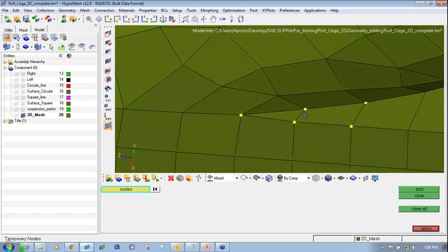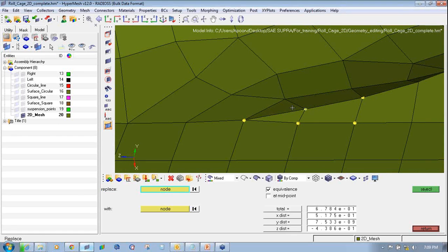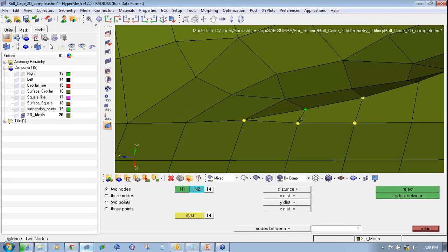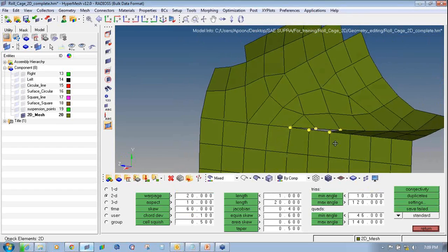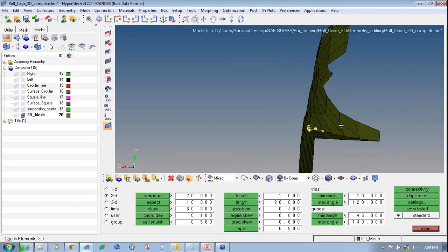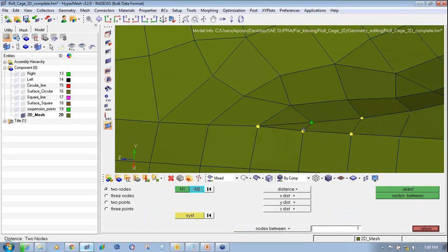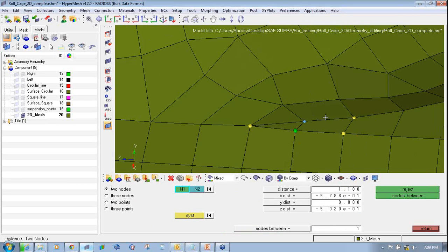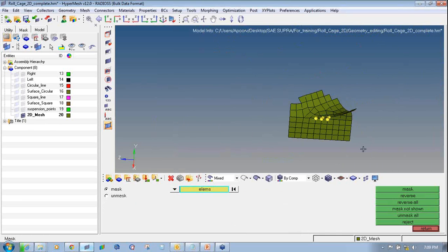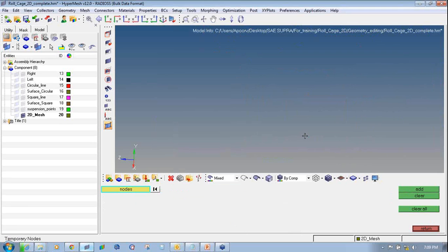Similarly on this side also you can see the length is very less. So if I press F4 for find a distance, it is coming as 1.6. So either I can increase our distance little bit or I can delete it. So instead of deleting it, I can just increase the distance a bit from 1.1, a little more. So it will pass the quality criteria. Anything more than 1 is okay.